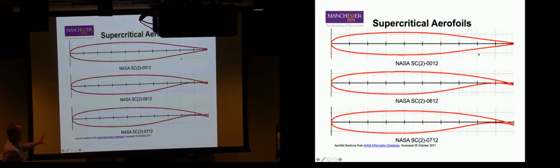But the nice thing is, because I'm not generating a lot of lift here, I don't have to accelerate the air as much. Remember, to generate lift, you need a pressure differential. To get a pressure differential, the air has to go faster, the fluid has to go faster. And to do that, we're getting closer and closer to higher Mach numbers. And then when we slow that air down, the flow at the back of the wing, we drop it back through Mach 1. What do we need to get back down from above Mach 1 to below Mach 1?